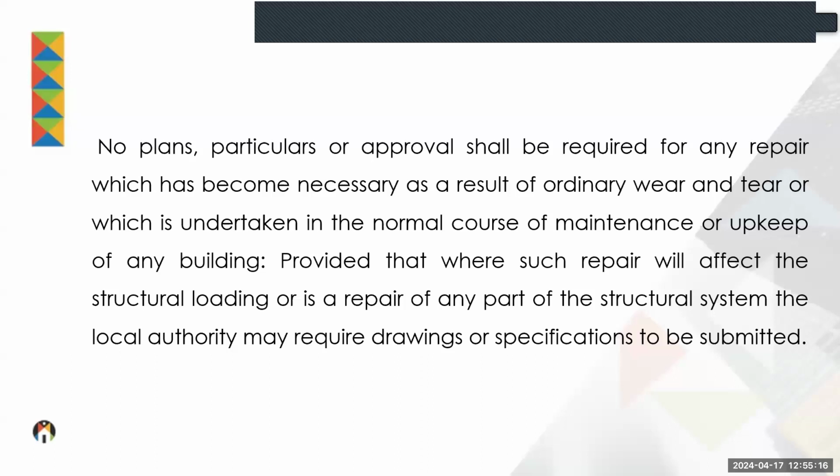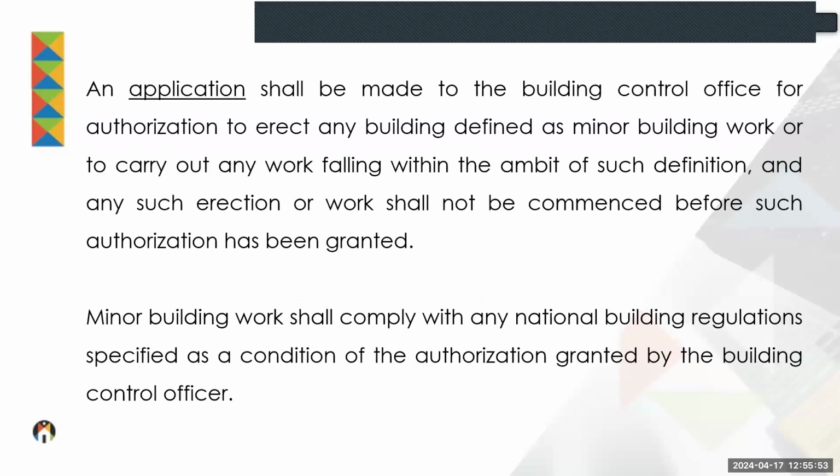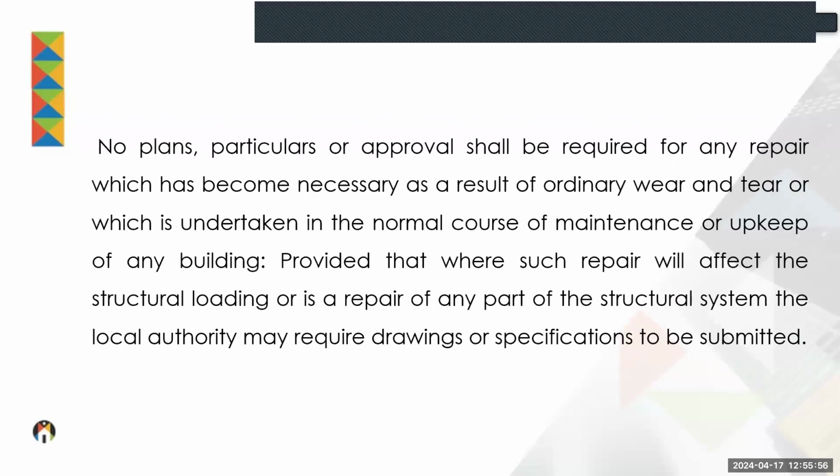Again, based on a court case here, if you replace what is there with what it was previously. So if you replace timber windows with wood windows, fine, no plans are required. But today we have envelope requirements in place as well, XA, for instance. So if you replace a timber window frame with a steel or aluminium window frame, you did indeed alter the envelope of the building. You did not keep it intact or similar to what it was previously, and the court case now says that plans need to be submitted showing compliance with Part XA, for instance.